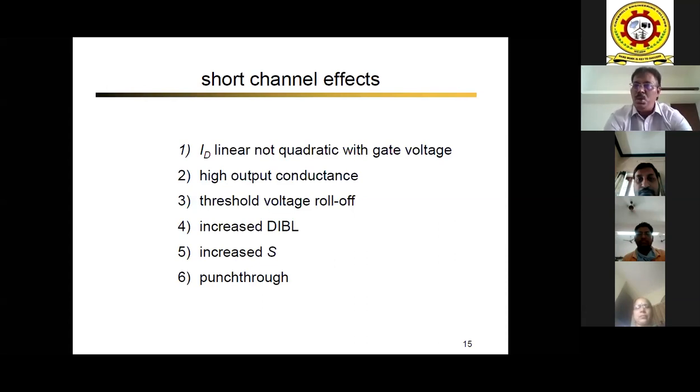Thereby, new terms are coming in. Earlier, the mathematical models we have been using, BSIM, Berkeley simulation models, are all based on conventional drift diffusion models. Now, quasi models are available, ballistic models are available, different kinds of models are available because we are now considering quantum mechanical effects as well in our models. And then apart from classical models, we even incorporate quantum mechanical confinement models.